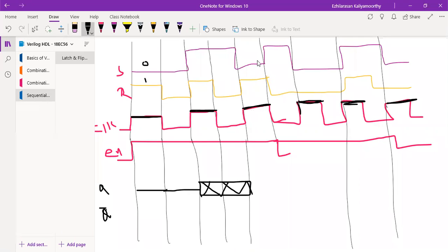Yeah. Now you can see this. It is level high. 0 and 1 means what will happen? I'll get a 0. This 0 will be till where? Till the next level. In this level, 0, 0. Again 0, 0 means what? Previous value, that is no change. Now the previous value of Q is 0. So this 0 will be maintained till next.